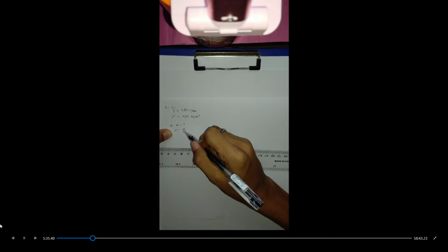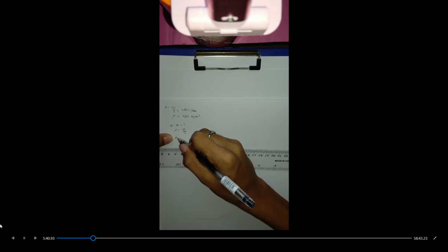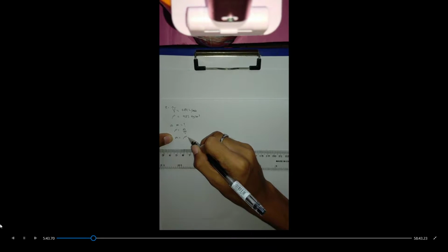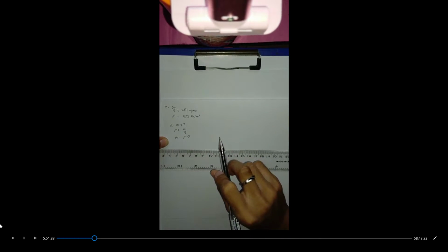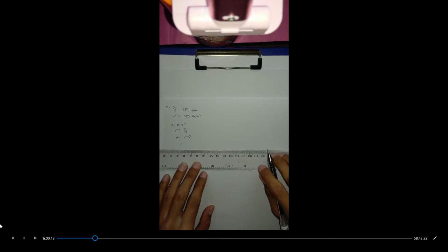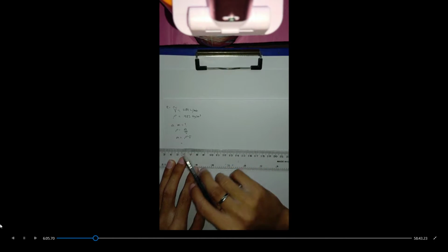We know that density is defined as mass over volume. If the given volume is a volume flow rate, then if we transform the formula into mass flow rate equals density times volume flow rate, the value we get will be in mass flow rate form. So in solving for the mass flow rate, since we are given the volume flow rate, we just use this formula and substitute the values.